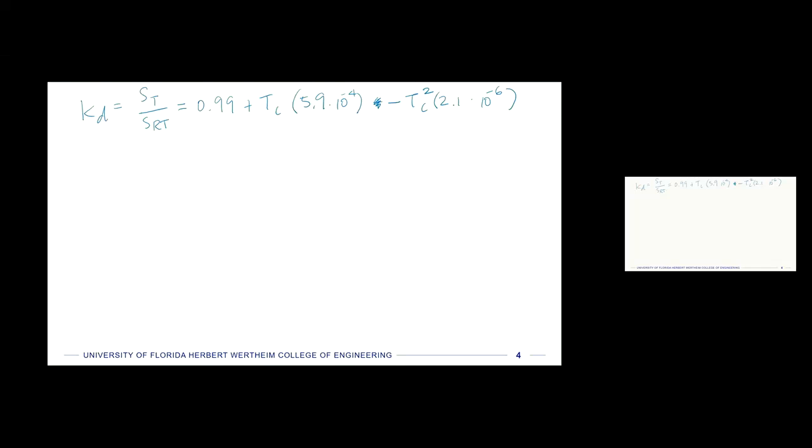Just of note, this is for compensating for temperature if you only have experimental curves or data that was taken at room temperature. If you somehow magically have curves for your exact material, these S-N curves taken at a high temperature, then you don't have to compensate for temperature after the fact. So only compensate one time. And then the last factor is that reliability factor.